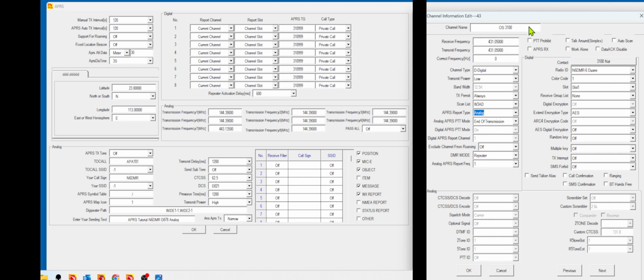And when you set these three sections of the channel, when you turn to this channel and you have this channel on an active VFO, A or B, and you press the talk, this is going to initiate APRS. Now it's going to do it in 2 ways. First, as we said, on the manual transmission side, it will send, and I've chosen here end of transmission. So when you key up, you're talking. When you unkey, it will then send an APRS manual transmission in the background. And these are going to be going out to the channel 144.390, which is the US APRS analog frequency nationwide. Okay, so this is how the channel and the APRS menu interact.